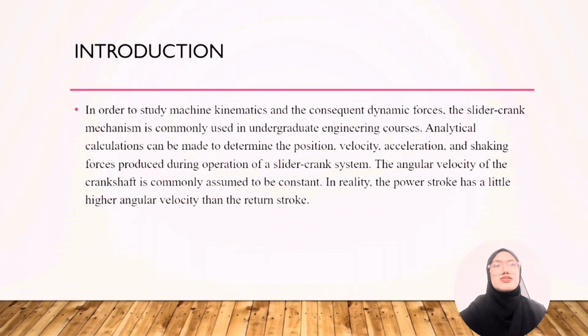In order to study machine kinematics and the consequent dynamic forces, the Slider-crank mechanism is commonly used in undergraduate engineering courses. Analytical calculation can be made to determine the position, velocity, acceleration, and shaking force produced during operation of a Slider-crank system. The angular velocity of a crankshaft is commonly assumed to be constant. In reality, the power stroke has a slightly higher angular velocity than the return stroke.